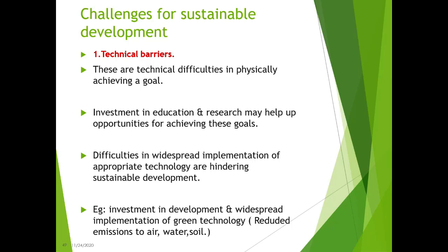For instance, I'm not going to go into the detail of the chemistry again, but if you use calcium carbonate filters, the calcium carbonate will react with sulfur dioxide to form calcium sulfate, which is known as gypsum, alçıtaşı. It is used in many different industries as a raw material. So you will not only get rid of those hazardous emissions, but you would also obtain a useful byproduct. So it's a win-win.